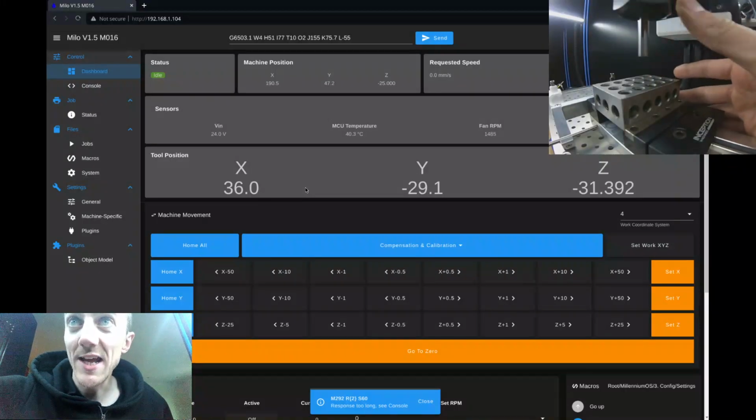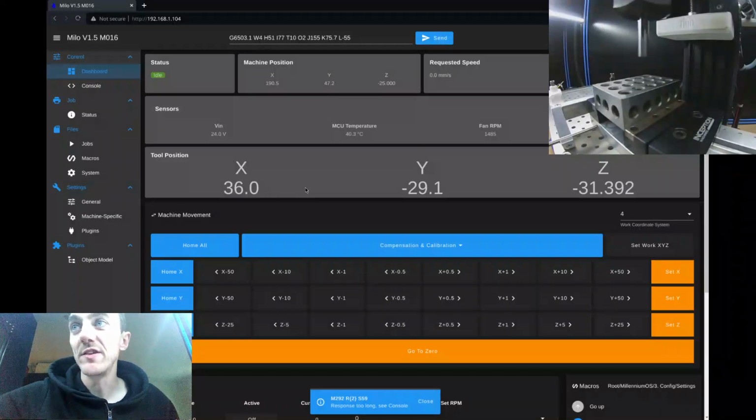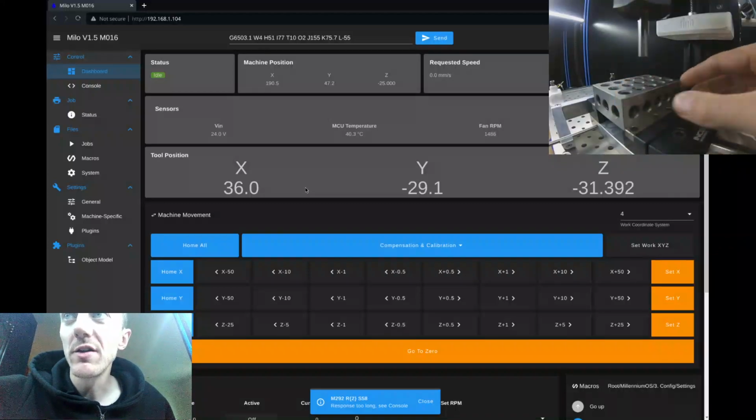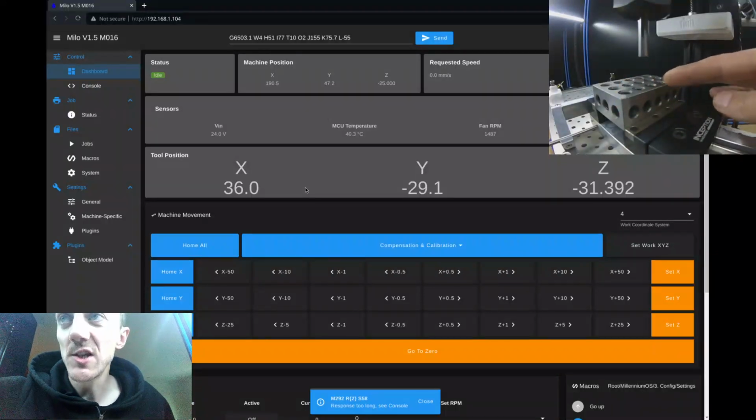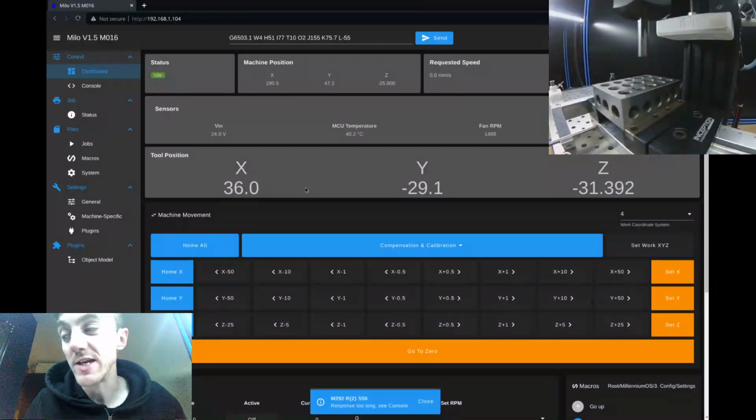That has already had its length probed by the tool setter, which is over here. But that is unimportant for this because we're not going to be probing Z heights. We then have a 1, 2, 3 block with a 3-inch side along here, so this is along the Y-axis, and a 2-inch side along the X-axis, and it's installed in the vise, and it's relatively straight.